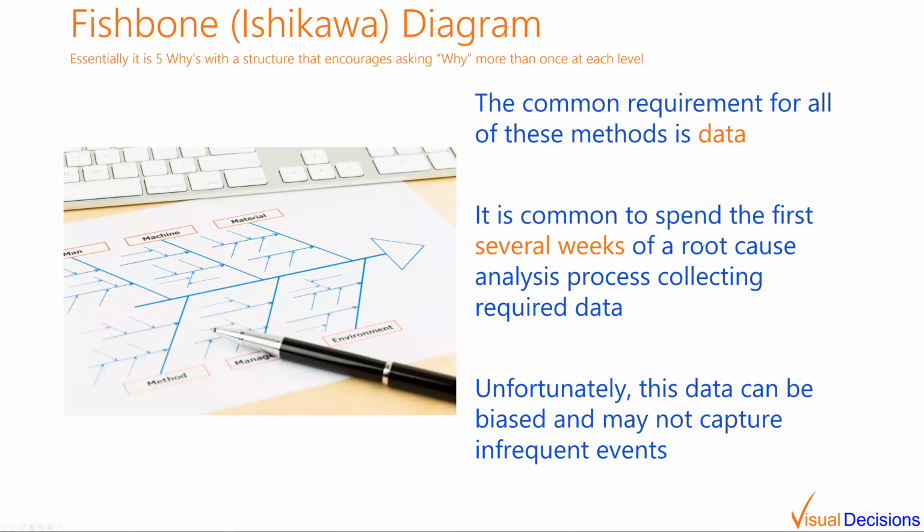And what you end up with is more of a tree structure for, what are the different reasons why it can fail, and then what are the different causes for that. And then, for each one of these different branches, you end up with different weights, different probabilities of that cause of failure. And so the Fishbone or Ishikawa diagram is really just a 5Y type of analysis, but going through it with much more rigor and looking at multiple reasons why it fails.